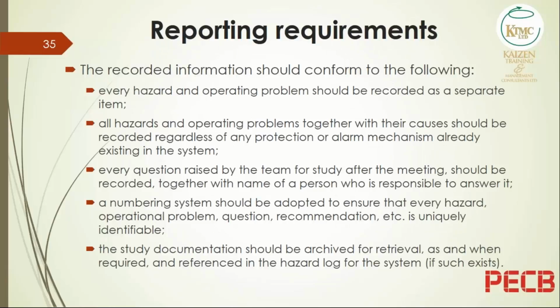The reporting of the results should be prompt, but time should not be a factor in being thorough. So the time specified should be adhered to as much as possible, but the quality of the report should not be compromised. Every hazard and operating problem should be recorded as a separate item. All hazards and operating problems, together with their causes, should be recorded regardless of any protection that may be in place. So yes, there are mitigation measures in place, but it should be recorded nevertheless.